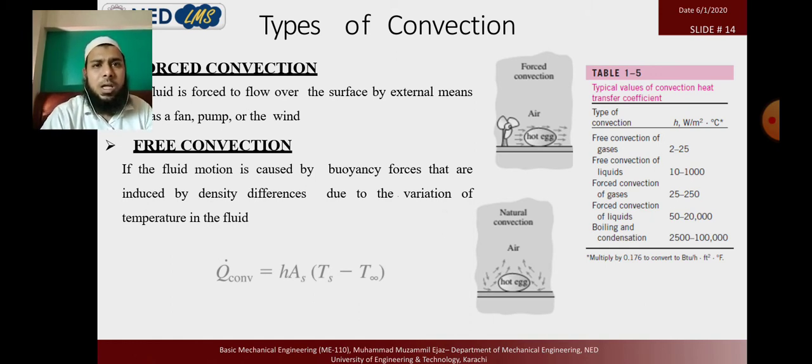The disadvantage of the natural convection cooling plate in the fridge is that we find a cold layer on the cooling plate. We have a layer of icing, an ice layer on the cooling plate, which resists the heat transfer, because ice has a low heat transfer as compared to metal. So bare metal contacting the air absorbs more heat, so heat transfer will be higher, and it has a better efficiency.